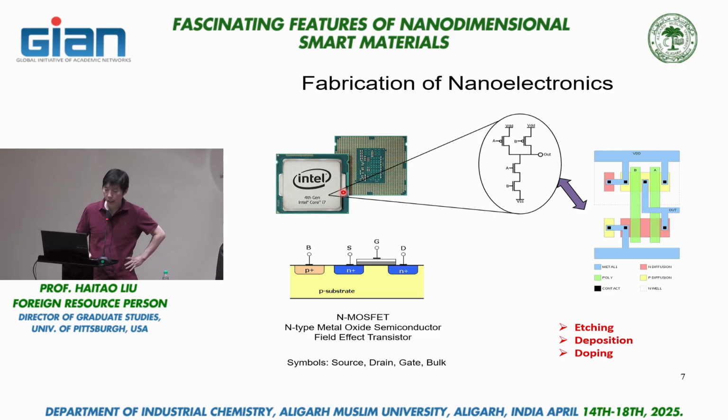Now, if you look beneath those packaged structure, what you're gonna find is a lot of transistors, essentially, or MOSFET. Now, you're typically shown this kind of electrical engineering diagram, but on the chip, what you see are something like this. You have doped region of silicon, either p-doped or n-doped. You have gate electrodes, and you have gate dielectric, and you have interconnects.